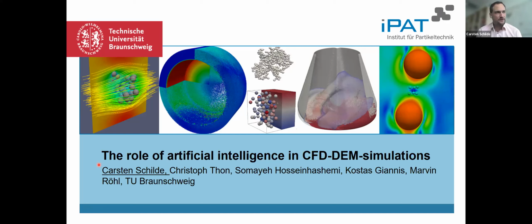But in order to have a good prediction, via, for example, machine learning approaches again, he then cut out 1 slice out of the mill to reduce the number of particles in simulation, just simulating 1 slice on the larger mill, as well as on the smaller, with the smaller grinding beads, the same mill, but the larger grinding beads and the smaller, in order to make this prediction a little bit more reliable. Not to predict within a black box, also have a kind of simulation on the small scale, but only a small slice out of the mill.